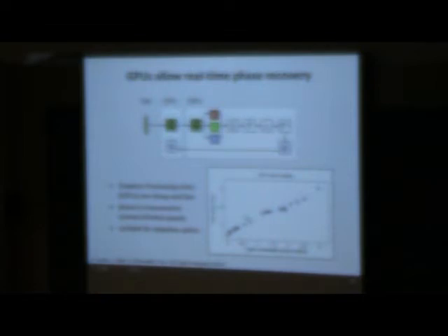I don't know if they design it. Sorry, your camera is essentially a black and white broadband camera with RGB filters on top of it. Right? So does the specific spectral transmission characteristics of the filter factor into your calculations there? It does a little bit, in that what we use as RGB has to be the spectrally weighted mean of the red channel, the spectrally weighted mean of the green and the blue. And actually, because of the Bayer filter pattern, I had intended to use a Foveon camera because each pixel measures all 3 colors, which is good, right? That should solve all of those problems.